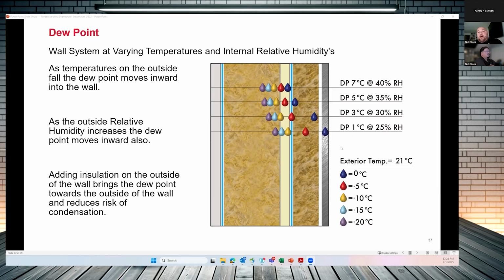Now, for down in Texas, that minimum R-value is going to be right around 5 on the outside when you have your standard, mostly 2x4 wall down in Texas, where you have an R13 or an R15. And certainly code is looking at that R13 and 15 marker with that exterior insulation on that.